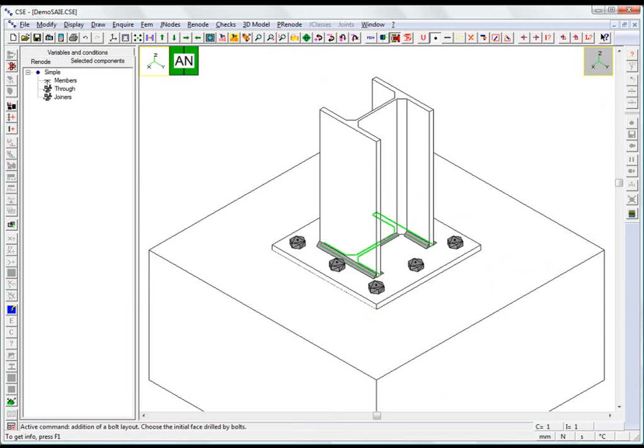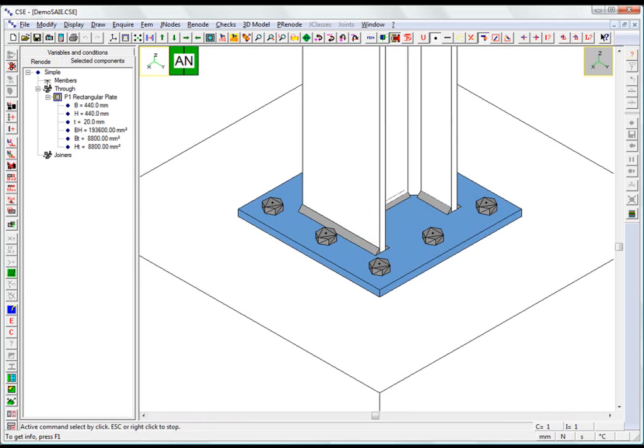The bending is transferred from this initial surface to the bearing support thanks to the bending stiffness of the plate to which the bolt layout is connected. In order that this plate can successfully transfer the normal stresses involved, it must be sufficiently stiff. The plate's stiffness depends on its thickness and on the geometry of the connection. A plate will be stiff enough in all its points if it is thick enough.